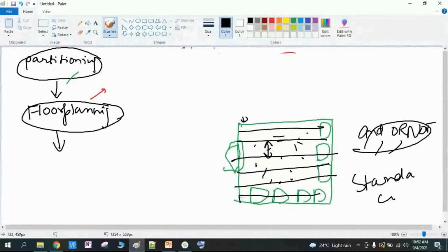After floor planning itself, you can have delay issues. The reason is, for example, there are guidelines to place these macros, as I told you. Let's say these two macros are communicating with each other, which we can check in the tool itself. If by mistake you have placed this macro here, see, it's all about future prediction. If you place macro 1 and 2 here, and if this 2 is placed there, where do you think you will get more routing issues?